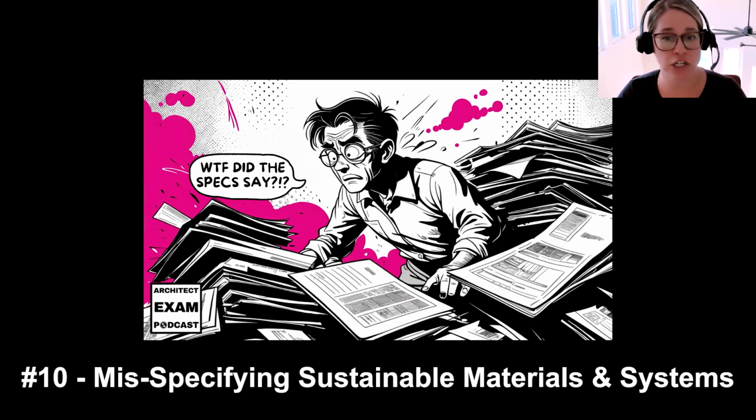So I've worked on a LEED project before where we specified low VOC paints, but I actually missed in the specification writing specifically the test requirement and acceptable limits in the specifications. So when the contractor submitted product data, it didn't clearly state the VOC content. I think that they had just kind of used something similar to, oh, this is what we've used before. And this submittal criteria was essential for us to fall into compliance for LEED. We didn't want to lose any of our LEED points, right?